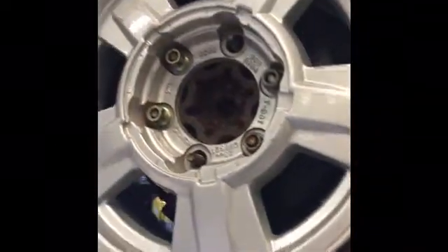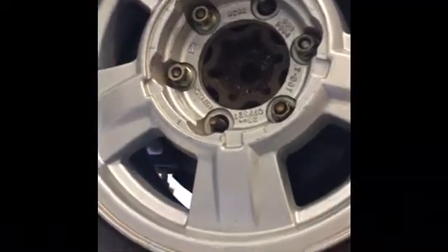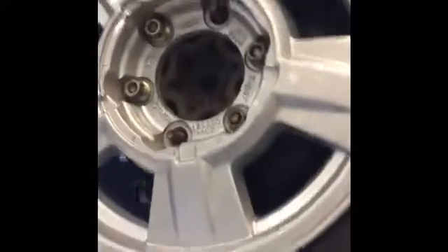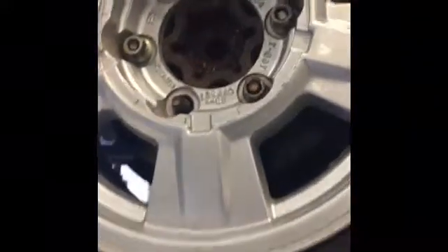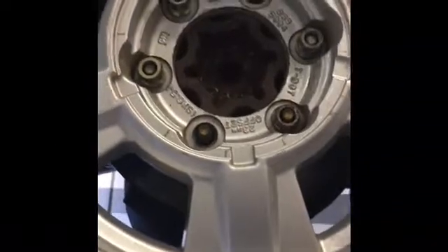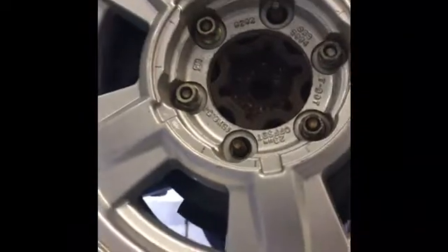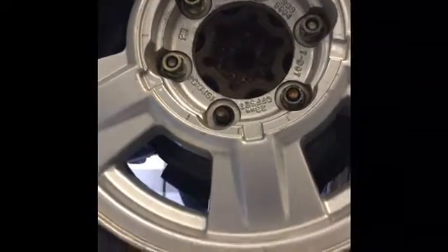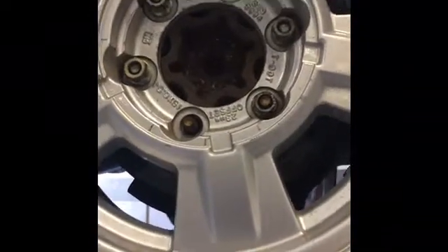Most vehicles have two different types of braking systems. Usually you have a disc brake system and a drum brake system, and on the front tires of this vehicle you have a disc brake system. A disc brake system has a rotor that is connected to the wheel hub, and on the rotor sits the actual disc brake itself. The rotor and the disc brake turn with the wheel hub, all in the same motion, and that way when you hit the brakes, the disc brake just squeezes the rotor and creates contact, and that's what causes your vehicle to stop.